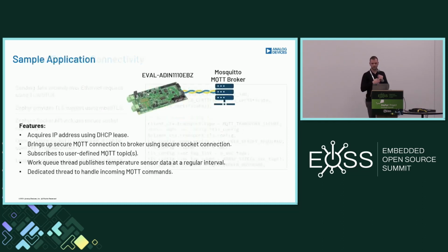Okay, so I just want to highlight an application that I've spent some time working on recently. I currently have a PR open to merge this as a sample application upstream. It really serves as a reference design for customers looking to get started on 10BASE-T1L connectivity. I've tested this on the eval kit for the ADIN1110, and it pulls together software with some of Zephyr's key components, including MQTT and DHCP.